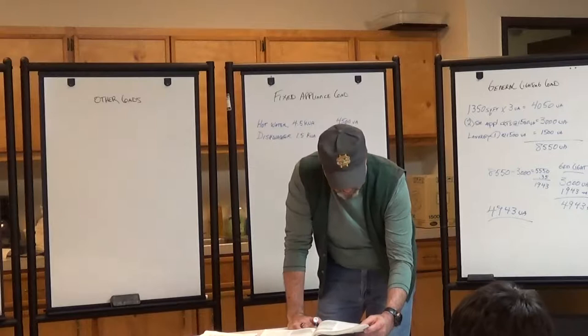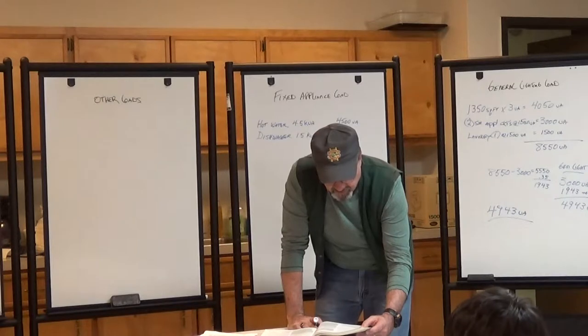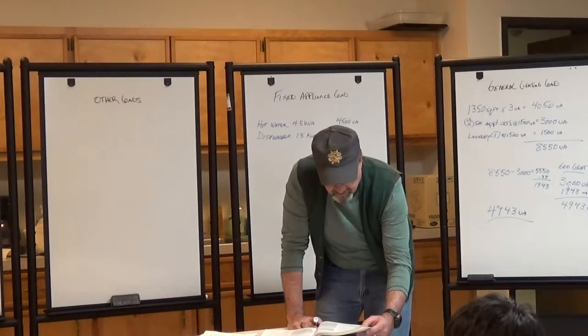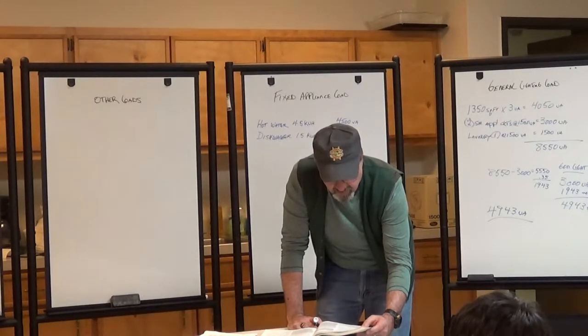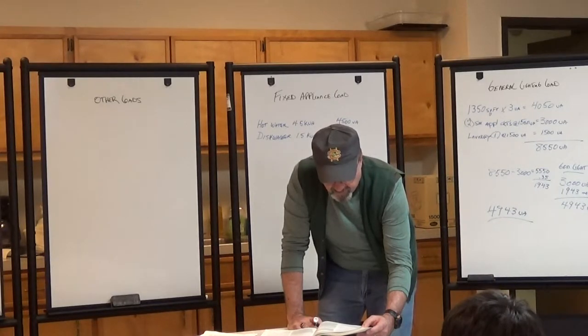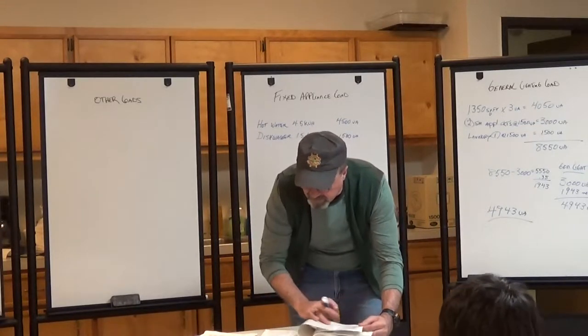Robert said page 70-316, Article 430.17. In determining compliance with 430.24, 430.53(B), and 430.53(C), the highest rated or smallest rated motor shall be based on the full load current as selected from Table 430.248, Table 430.247, Table 430.249, or Table 430.250.